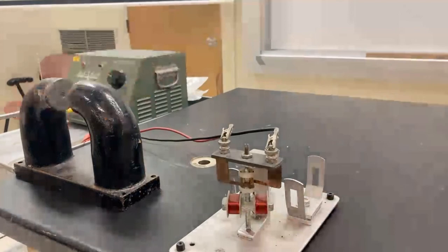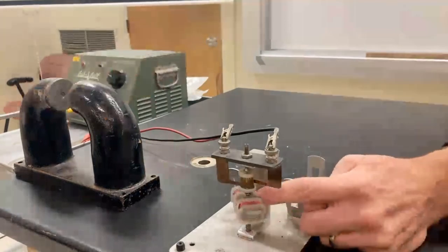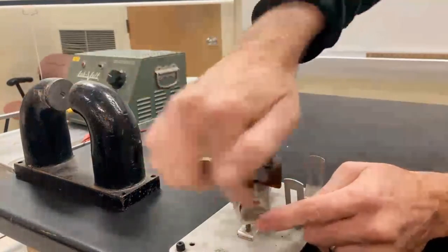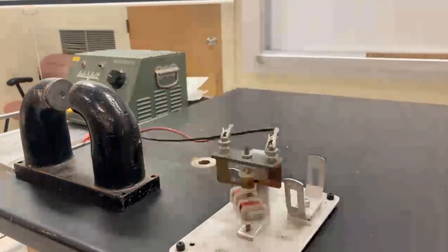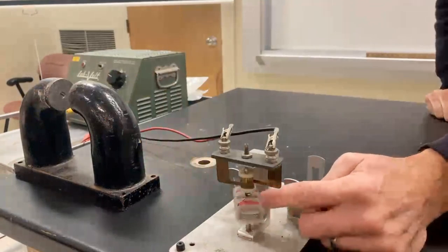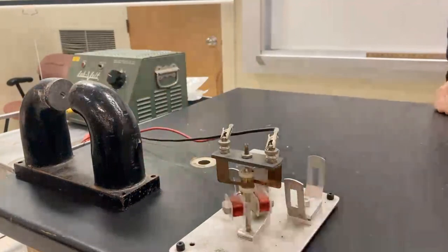So this is free to rotate. So it's going to rotate. And when it rotates through 180 degrees, it changes which of these two electrodes comes in contact with the positive terminal. So it reverses the direction of current. And now it gets a torque in the opposite direction, and it will try to rotate another 180 degrees to align to the magnetic field. And then that whole system repeats, and we've got an electric motor.